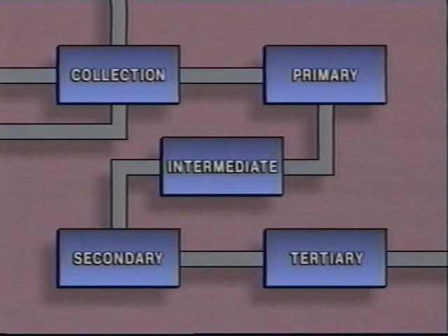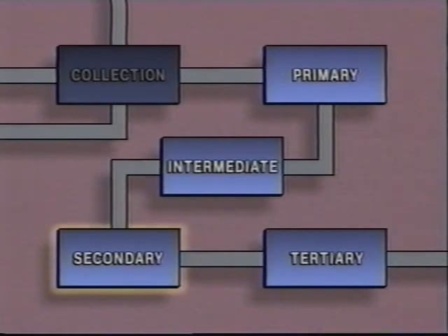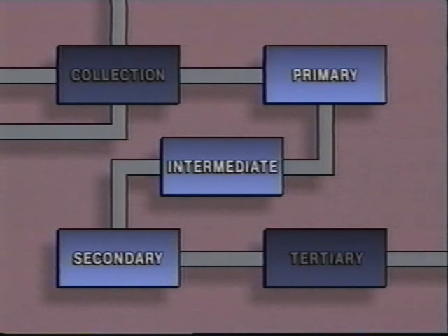Before we decide how to proceed, this is a good time to check our progress so far. Since the condition of the wastewater fed to this collection system is normal, we can rule out the collection area of the system as the cause of the level problem downstream. The problem was first detected at the secondary clarifier, so we can eliminate the equipment downstream of that, the tertiary treatment stage. We also check the recycling and wasting rates of the activated sludge, as well as the operation of the secondary clarifier. So we can rule out the secondary treatment stage too.